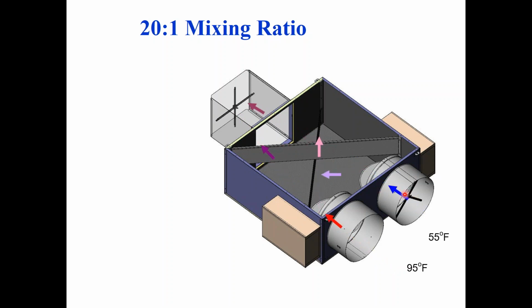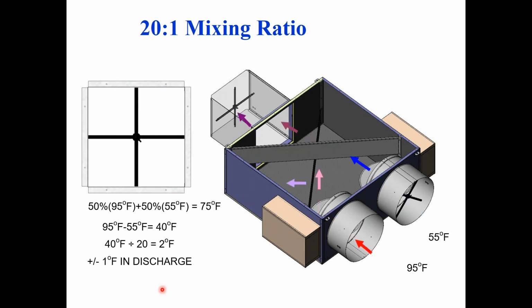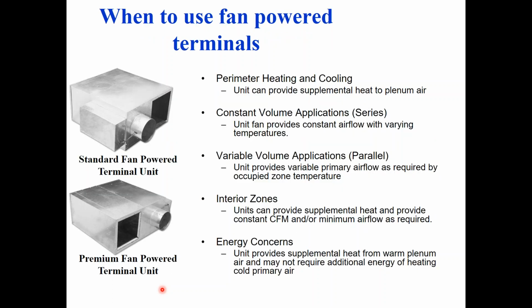You can see here there's actually an airflow probe on the inlet, and we'll talk more about those when we talk about controls here in a minute. And then I actually have an airflow probe on the outlet as well. I don't need one on the inlet of the heating, so if I know the inlet here and I know the outlet there, I actually can calculate the inlet of the heating if I really wanted to. So this is just showing some mixing examples, which is just basic math. So just showing you how good it mixes.